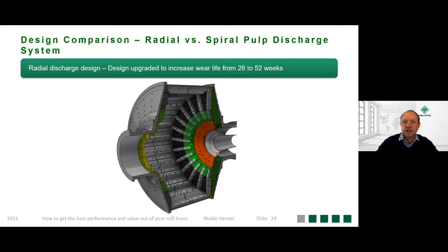And I also want to point out this scroll return or this return feed pipe. The function of this return feed pipe is to feed scats back into the mill. So Mohini has indicated that the pebble crusher connected with a magnetic separator, that is the most efficient way to get rid of scats, and I totally agree with that. But this system, the return feed pipe system where you feed scats back into the SAG mill, it either works for you or it doesn't. In this specific application, it works.